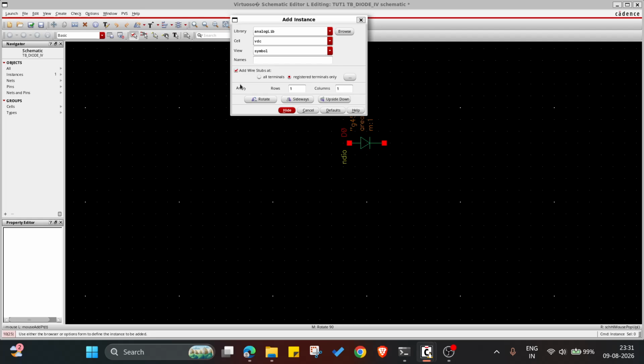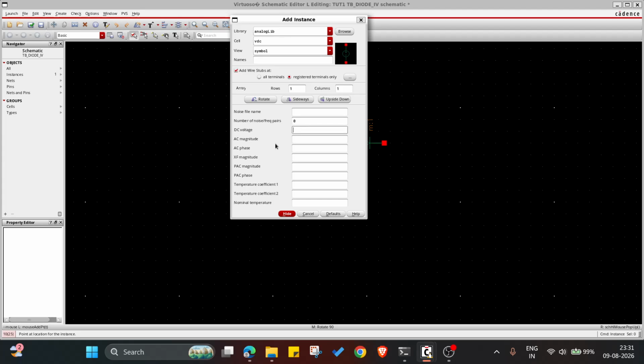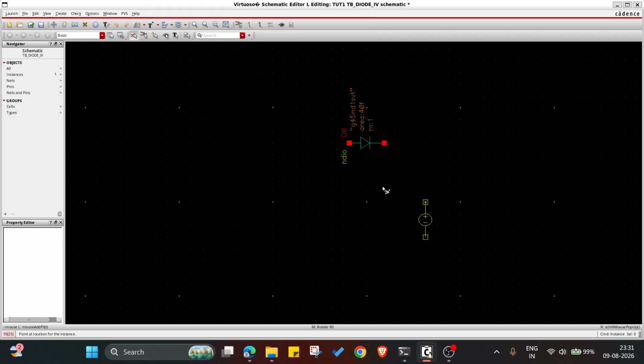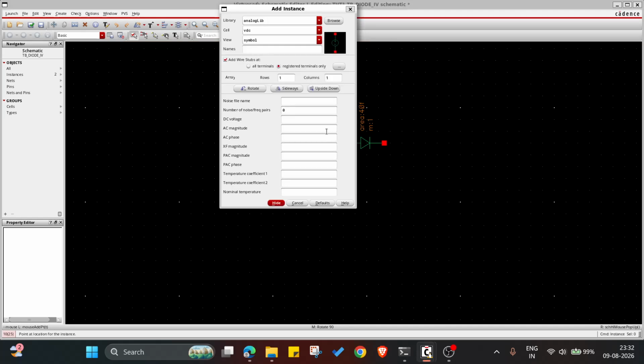Okay. So this DC source voltage we are going to vary and measure the current, right? So just click on VDC and mention the DC voltage as Vx, let's say. Okay. Now let us bring a ground.